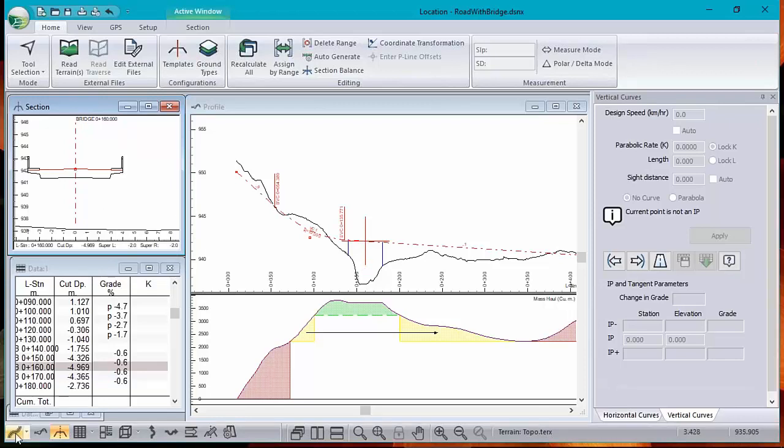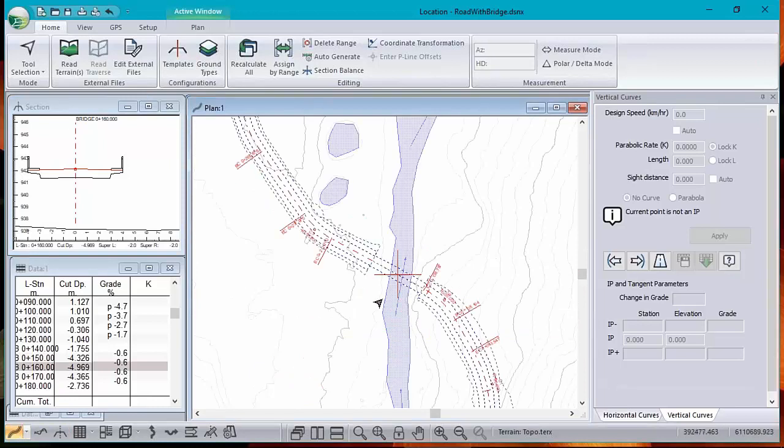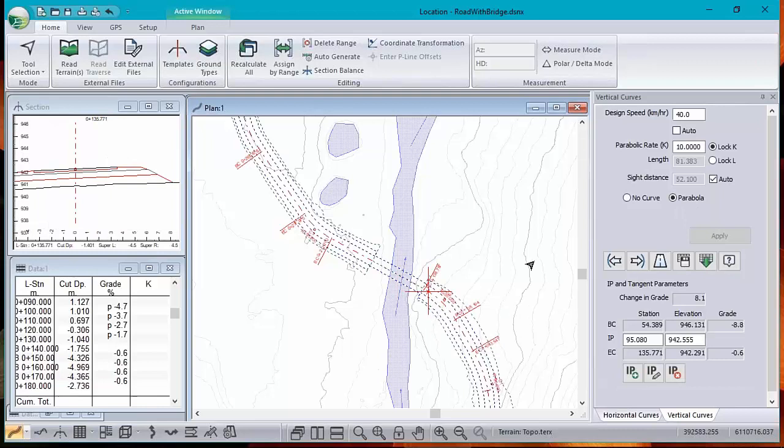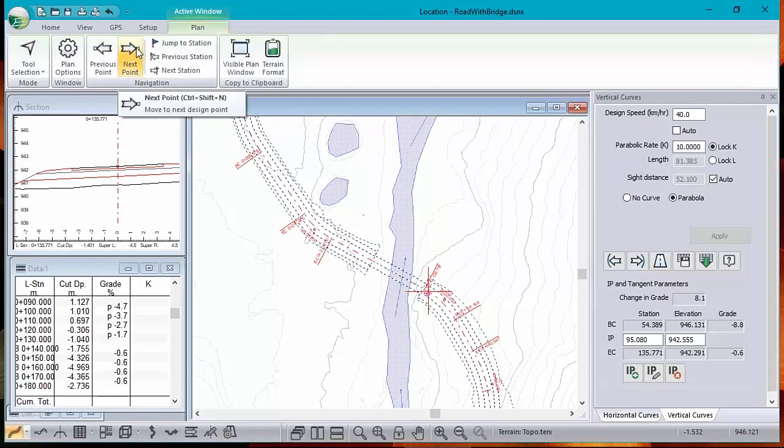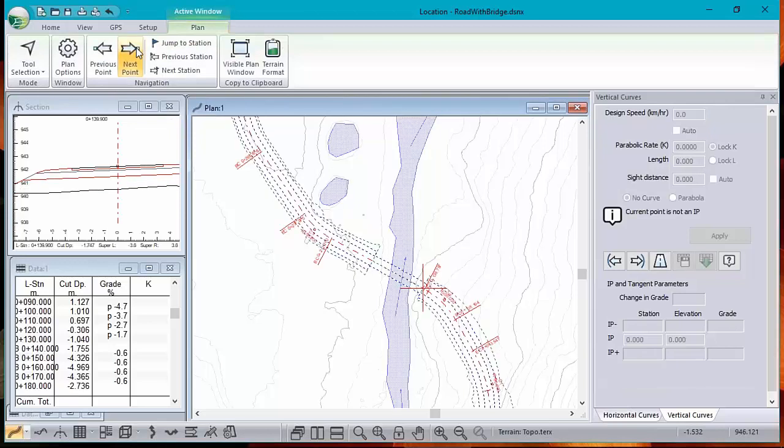Notice that I turned off any superelevation, so it's flat, and that's good. Except it turns out that in my plan window here, I have a curve that comes up really close to the bridge. So right there, you can see the cross section does have superelevation. And now, if I just go a couple of more stations, there it's still superelevating. It says it's got 3.8% superelevation, and boom, we're onto the bridge, which has no superelevation.